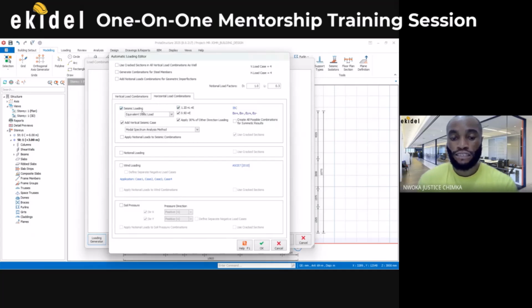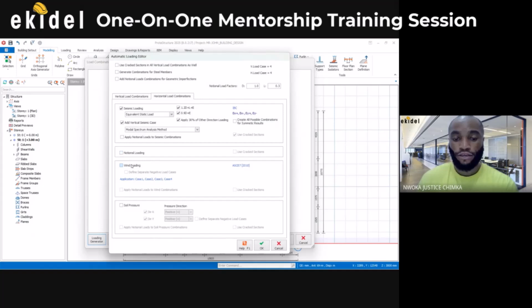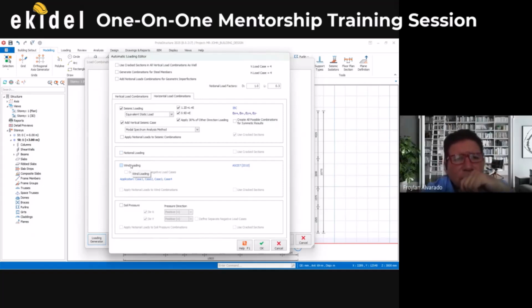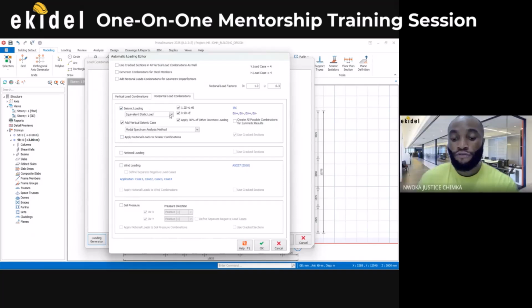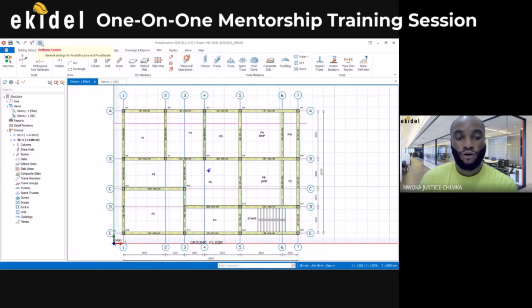Here you can see your seismic loading is already checked. If you want to add wind load, and you don't have seismic, like in my country, what you do is cancel. Just watch. I'll cancel this first and cancel again. Just say no, then come back to the settings tab here, and click on settings. Then it will open up the settings.